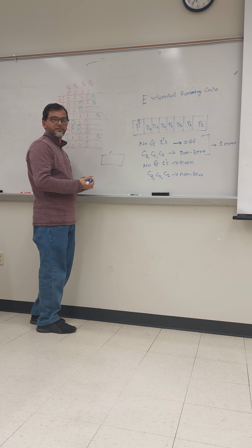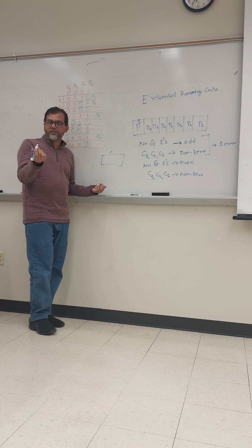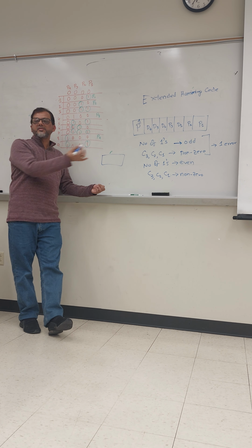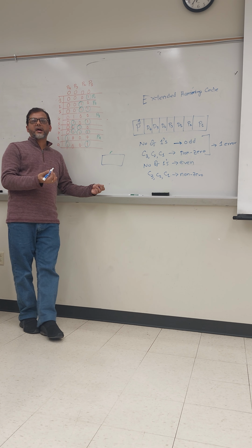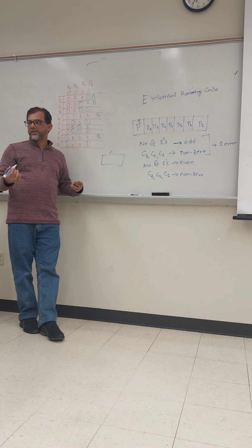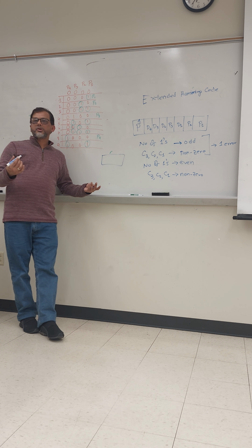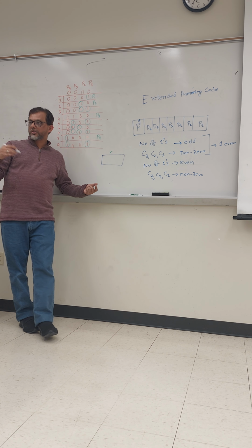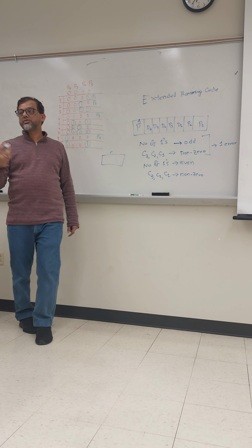Whatever we see, this is an IC, right? We call it a 7408 IC, or 7432 IC. This is an AND IC, this is an OR IC. But inside, what we have is an analog electronic circuit. This is all about the transistors inside, right? Usually we can use BJT transistors or MOSFET transistors. But those transistors are related to temperature and to capacitance. They form a capacitance, so if we increase the number of input signals, the capacitance will increase. It will reduce your speed. So those are the things we need to keep in mind.